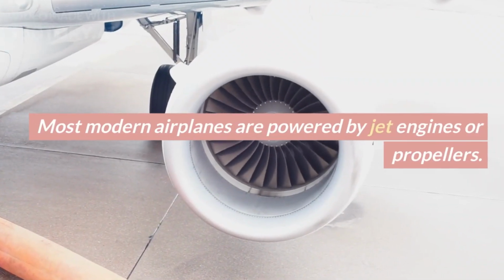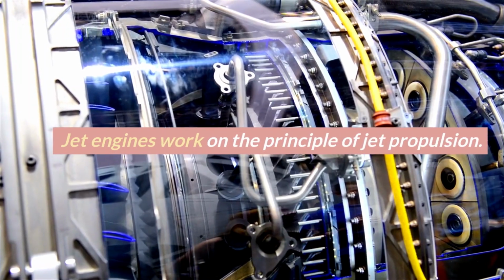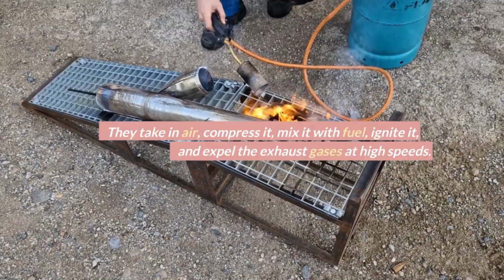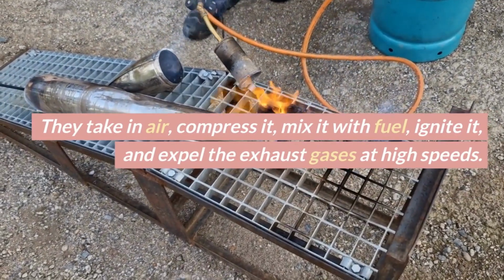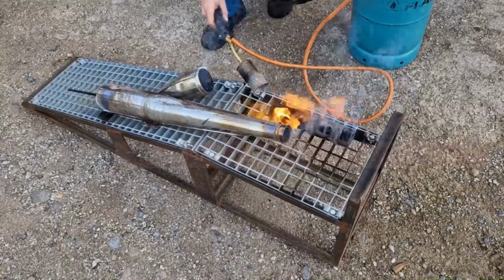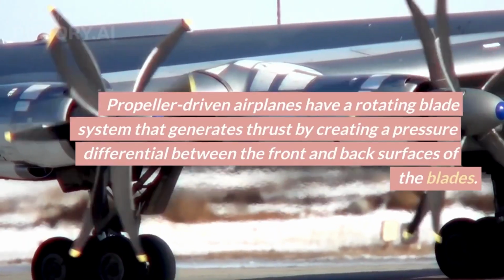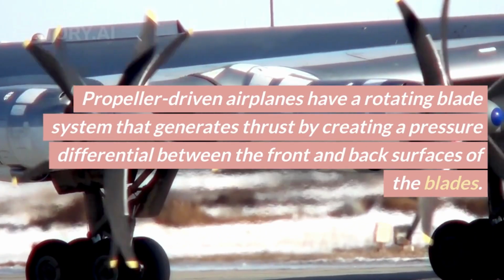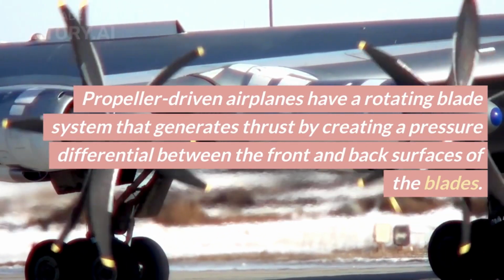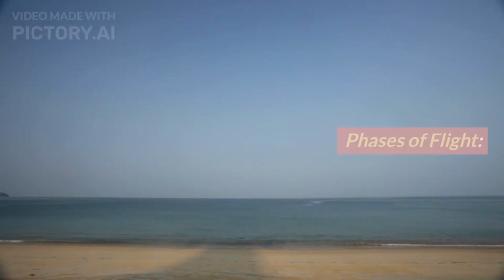Engines and propulsion. Most modern airplanes are powered by jet engines or propellers. Jet engines work on the principle of jet propulsion. They take in air, compress it, mix it with fuel, ignite it, and expel the exhaust gases at high speeds. This creates a forward thrust that propels the airplane. Propeller-driven airplanes have a rotating blade system that generates thrust by creating a pressure differential between the front and back surfaces of the blades.